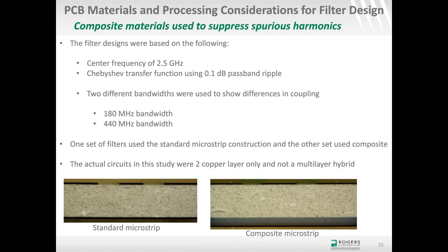And just due to that bandwidth, you will get quite a difference in coupling, where the 180 megahertz bandwidth filter will have loose coupling, and the 440 megahertz bandwidth filter will have tight coupling. So I wanted to show this concept with loose and tight coupling, so that's why I did that.